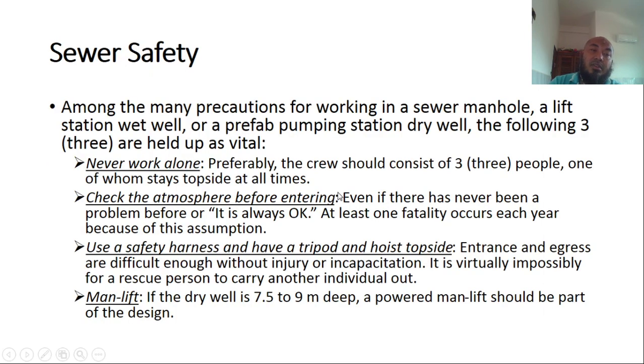Okay, we move to sewer safety. Among the many precautions for working in a sewer manhole, a sewer, or a lift station, wet well, or a prefab pumping station driver, the following three are held up as vital. Never work alone.